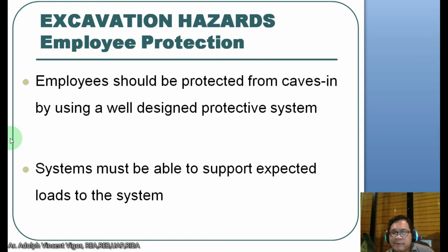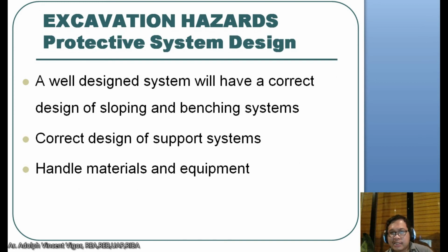So employees should be protected from cave-ins by using a well-designed protective system. The systems must be able to support expected loads. A well-designed system will have a correct design of sloping and benching systems, the correct design of support systems, and proper handling of materials and equipment.